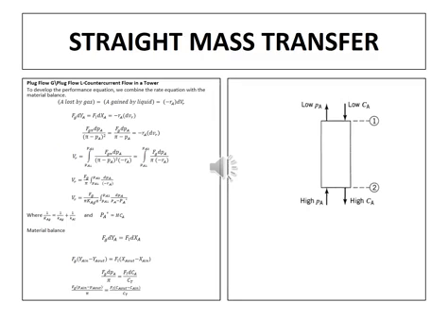The first performance equation that you're going to have is for straight mass transfer, a straight mass transfer reaction for plug flow gas and plug flow liquid in a countercurrent tower. So we need the material balance. The material balance is as follows: A lost by gas is equal to A engaged by the liquid, which is equal to our rate of reaction times dVr, and that would be that in terms of equations.